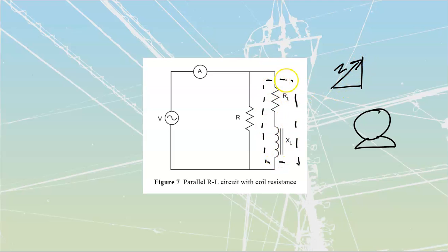If I take a look at the relationship these two have, these two are considered to be in series with each other. Which means I could get an R and an XL, and I could have an upwards Z like that. But then I would have to somehow place that Z in parallel with this R over here. That does get difficult to do accurately. It's not that it's hard to do, it's just hard to keep track of it and make sure you got everything going in the right direction. You could add this thing at the proper angle and this thing at the proper angle of 0 as well, right? Because it's resistive. But why bother with that if that's going to cause us issues?